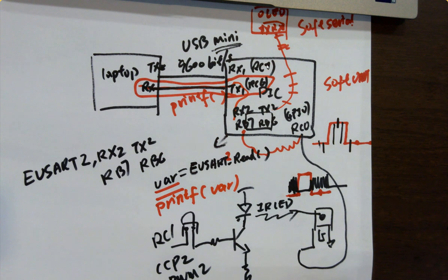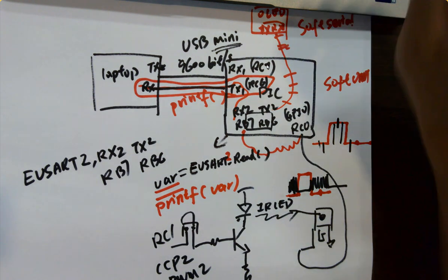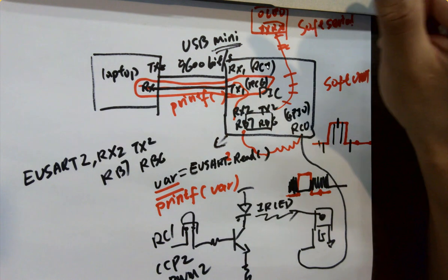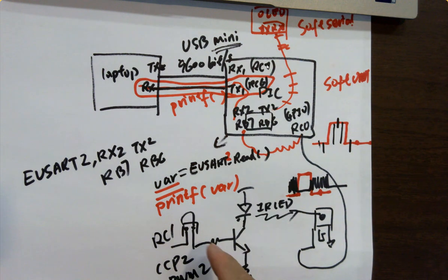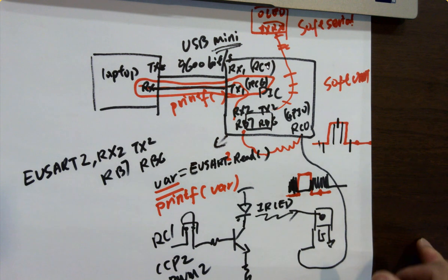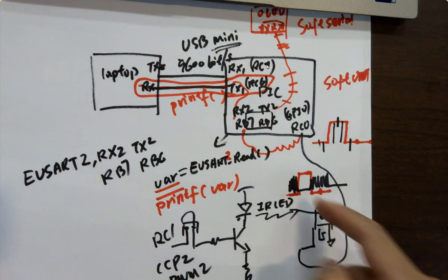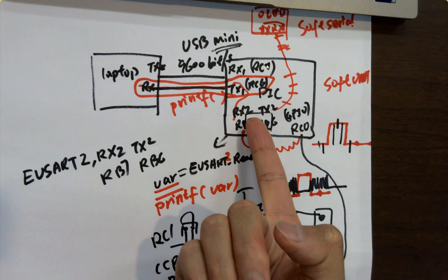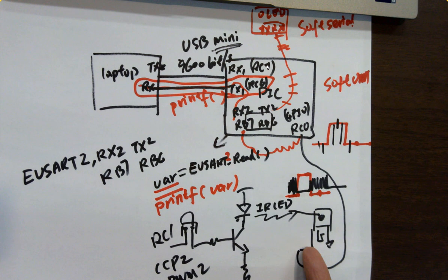If you are just sending one character, which is what the inLab does, you don't need to create a buffer. I'm going to show you what the buffer looks like. You press S, it's sent. You can't visualize it because it's IR. The decoder is already on, and because you have UART2 enabled, whenever a signal appears here with a protocol, it will receive it. So what's the starting bit of UART?